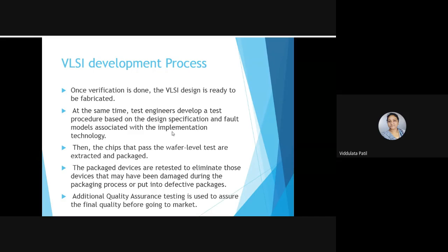Whatever circuit we have designed, depending on which testing procedure is suitable for it, they will develop a certain technique and then test that circuit. The chips that pass the wafer level test are extracted and packaged. So if the ICs pass this test, they are extracted and then packaged, and these packaged devices are retested to eliminate devices that may have been damaged.